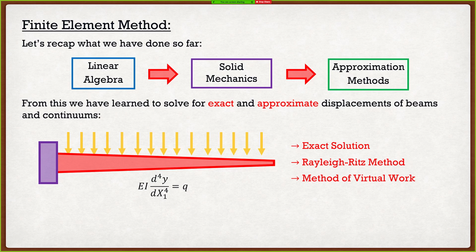The actual answer is no. This equation that we derived for the Euler-Bernoulli beam came from the idea that I was constant. We only obtained this equation under that assumption. So if I is not constant, the beam does not actually get governed by that equation anymore. So this becomes a problem. All those nice differential equations that we once knew and loved, well, they're no longer valid.